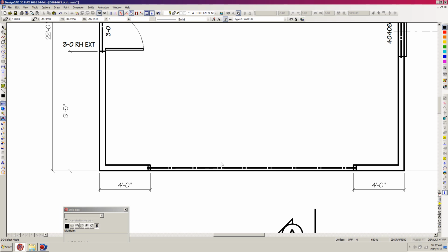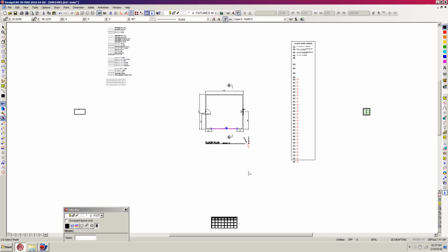A lot of times, for beams for like overhead garage doors and stuff, I also show an actual floor plan beam. And I think I will do it in this case. So I'm going to hit the rectangle or the 2D box command, which is the right bracket. And I'm just going to go out of orthogonal mode and click here. And I'm going to right-click the lower left trimmer on the left side, and right-click at the upper right trimmer here. And so I'm going to select that beam now and hit Control W.